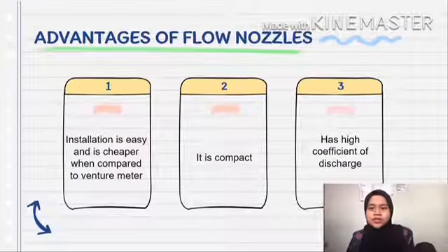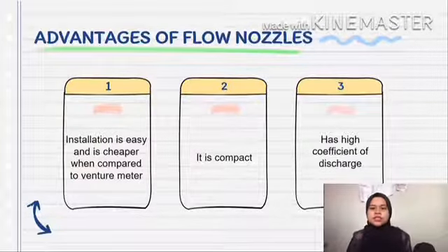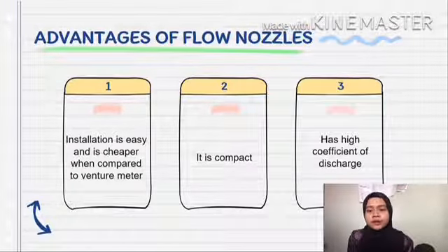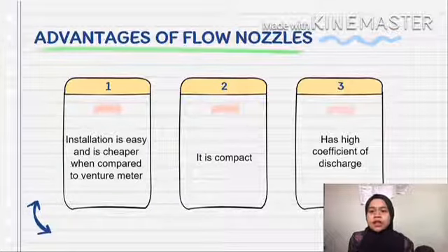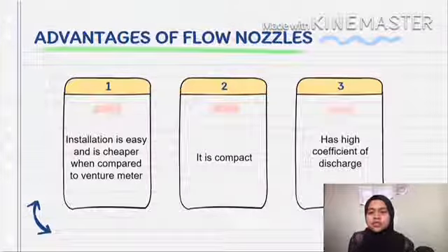Advantages of flow nozzle. First, installation is easy and cheaper when compared to the venturi meter. Second, it is very compact. And the last one is it has a high coefficient of discharge.